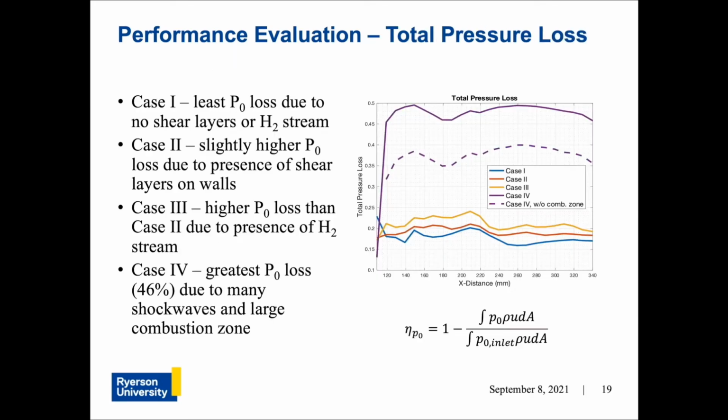Since flow across a shockwave is adiabatic, meaning stagnation temperature remains constant, and the process is both irreversible and non-isentropic, the total pressure must decrease, as entropy is a function of change in total pressure over total density and total temperature. Entropy also increases with boundary layer separation, further reducing total pressure.